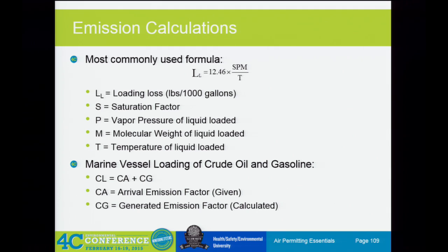Yeah, but for all those in the facility, you may have to do leak testing. At a large facility, you would have to do leak testing and the LDAR work. But for the truck uncontrolled emissions at a loading rack, you don't do those leak tests. You just represent those emissions and make sure that they pass impacts.